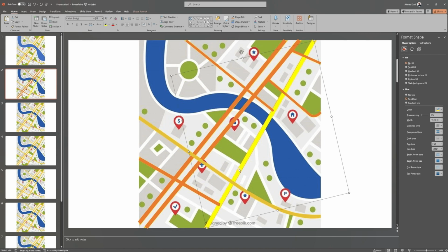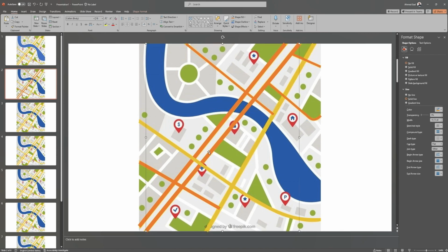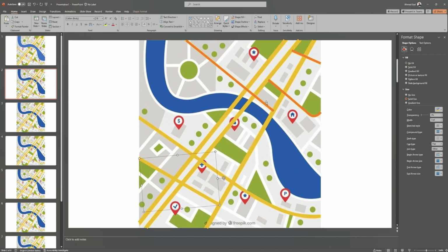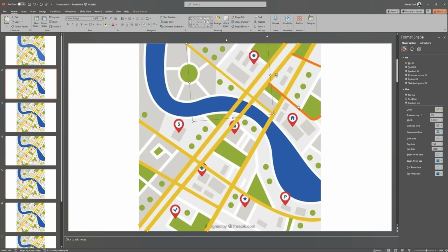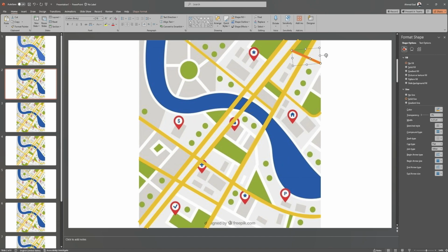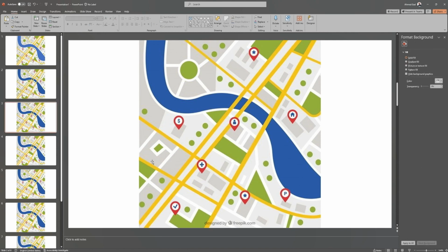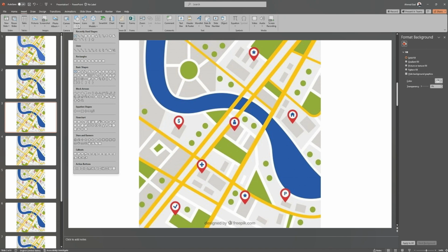You can just press F4 to repeat the recent process you did already, like giving the line colors. Just pressing F4 can repeat the exact process. Moving forward to selecting the green areas, actually representing the gardens and so on in the map, here I can utilize the circle selection.